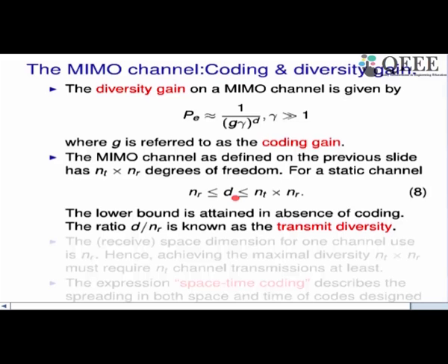So that's why you will have NR different replicas at the receiver. So that is going to be the minimum. Okay. So for the code that you use over MIMO, the maximum diversity order it can have is NT, NR, and the minimum it can have is NR.